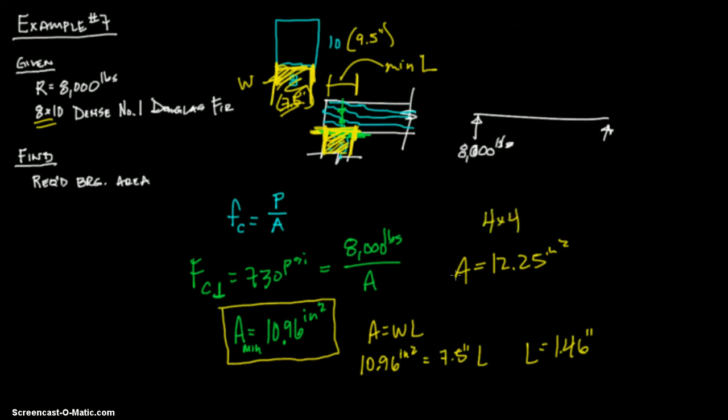But then again, if you're designing, you could say a 4x4 minimum or area equivalent or greater. And that would give you a little bit of factor of safety. Obviously, they're not going to put it directly underneath. Maybe they'll overhang it a little bit. What if they put it over here a little bit? It's up to the designer how you want to do that, and it's probably more dependent on the codes that you're looking at. But that's a little bit more of a real world example.